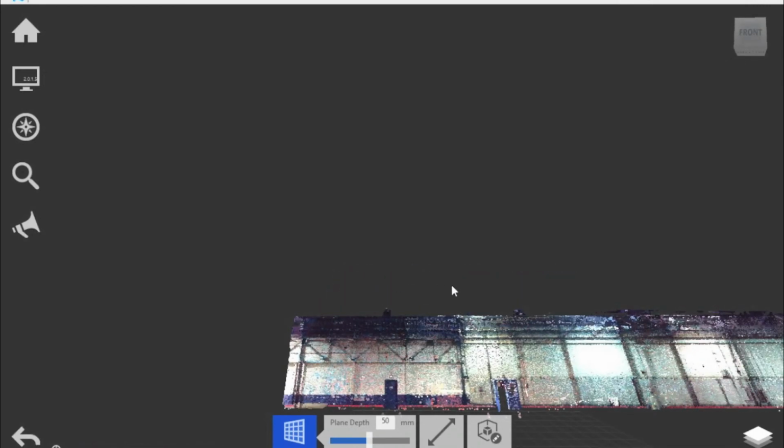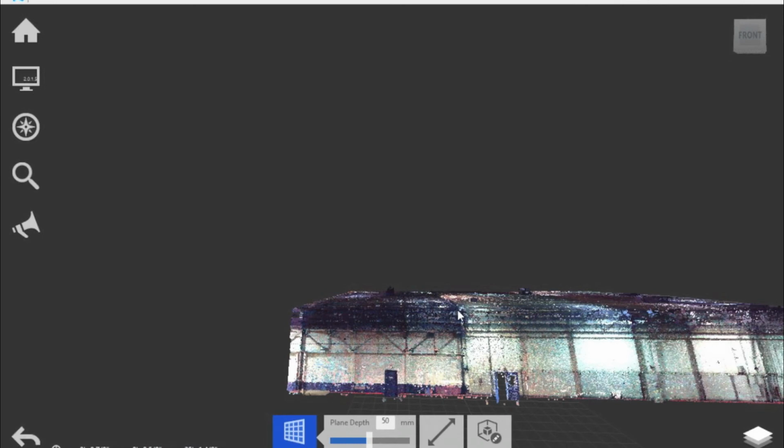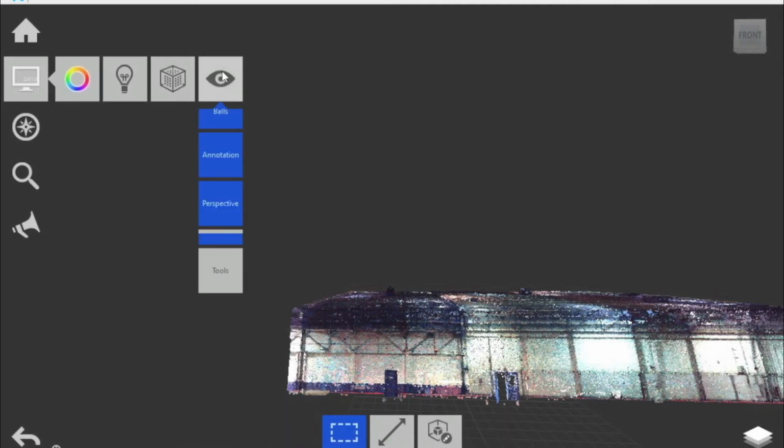All roofs have some type of slope to them, so you wouldn't select the entire roof. You can see that between columns, that's where your main pitches are. So I would only crop my view to that particular one. I'll show an example of what I mean. Let's turn my perspective off, look at it directly from a front view, and select column to column.